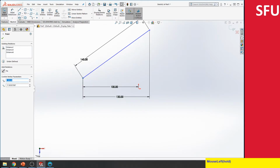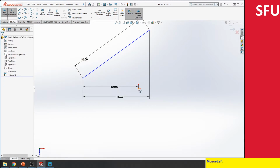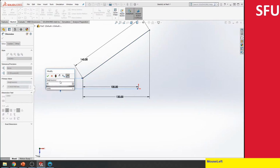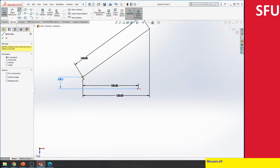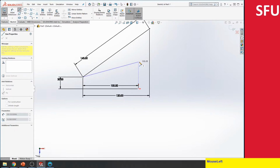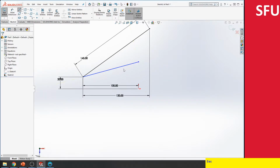So if I wanted to do a vertical constraint as well for the position, I can do that. Click on here and here. That gives a position. And then I can again change this value to say 20 just to make it look nice. So this is all of the positional constraint and the length constraint that we do. In order to do an angle constraint, you would actually need another line. So let's make sure we draw another line. Just assume it's coincidental at this point, and then you do again.